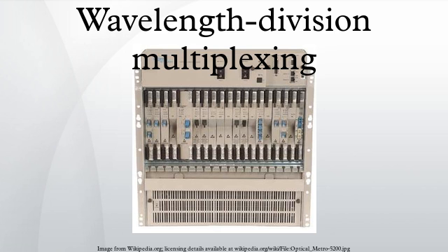Multiponder. The multiponder has different names depending on vendor. It essentially performs some relatively simple time division multiplexing of lower rate signals into a higher rate carrier within the system. More recent multiponder designs have absorbed more and more TDM functionality, in some cases obviating the need for traditional SONET/SDH transport equipment.